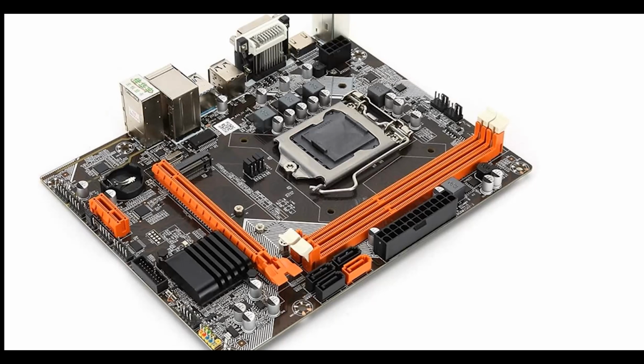And then to the left-hand side of the board, you see 2 PCIe connectors. There's a little short one, a PCIe, a single lane one. That's for connecting a Wi-Fi board or a network or a printer, a parallel printer, something like that that's slow, would happily go into that little PCIe ×1 socket, which is very, very close to the left-hand edge of the board. And then there's a big, long, orange PCIe ×16 socket. And that would take a fast graphics card or a GPU if you wanted to make a number crunching computer or whatever. Next to that, you'll notice an NGFF socket on the motherboard.